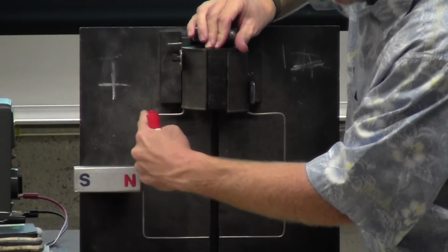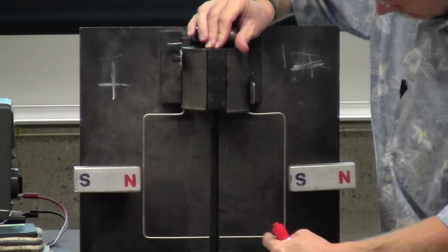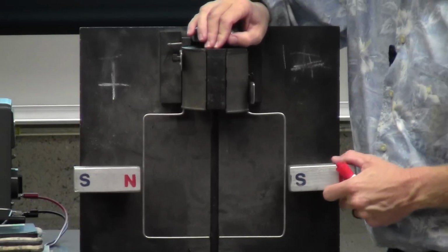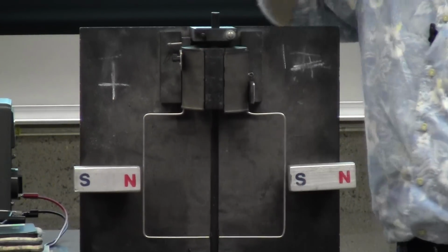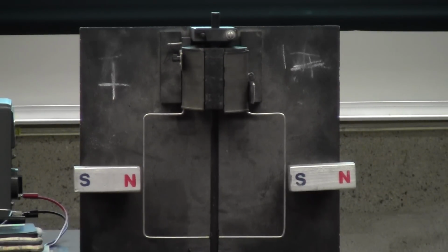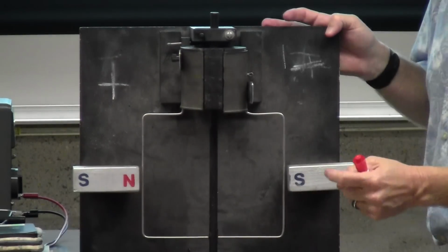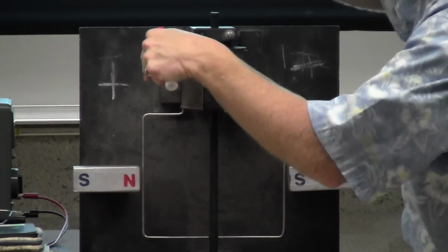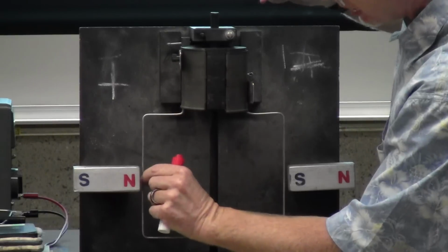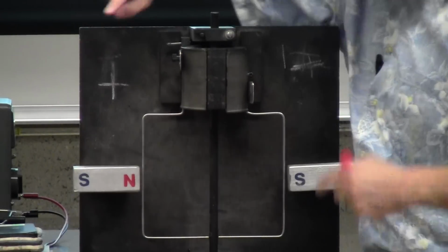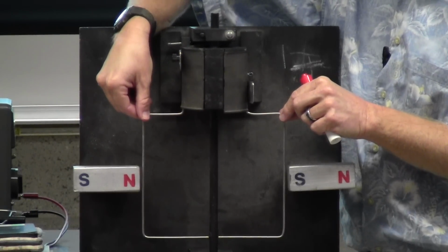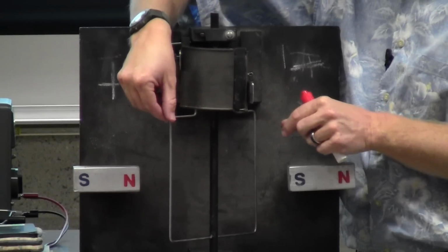The current goes down through and around the rectangular loop. And these colored pieces of wood are supposed to represent the magnetic. Obviously, this is not a real magnet here. But there's the North Pole, there's the South Pole. So the field is going across here, current going down and across. This wire has a force that way. This wire has a force this way. And wouldn't that then rotate it?